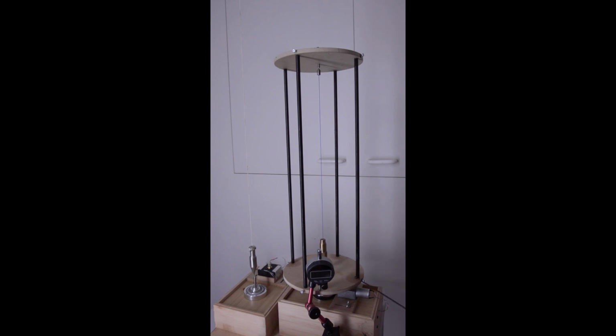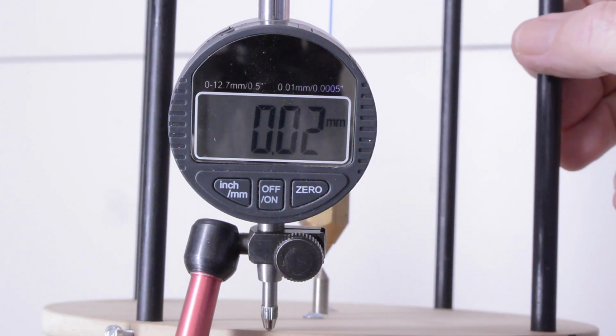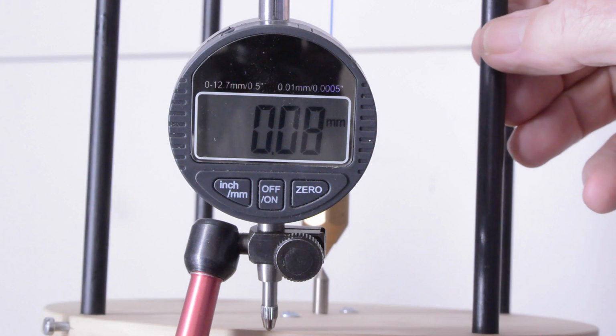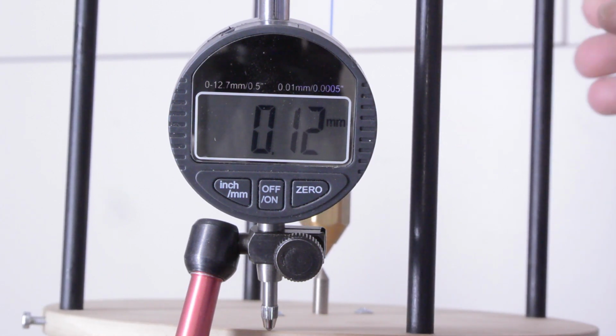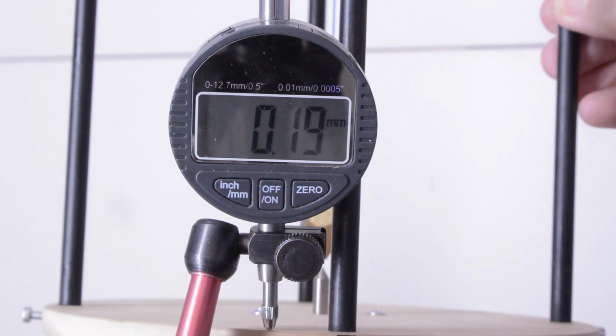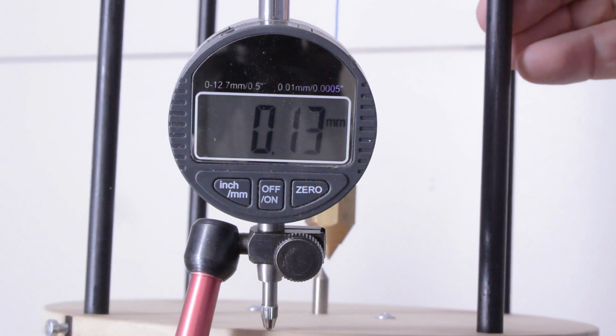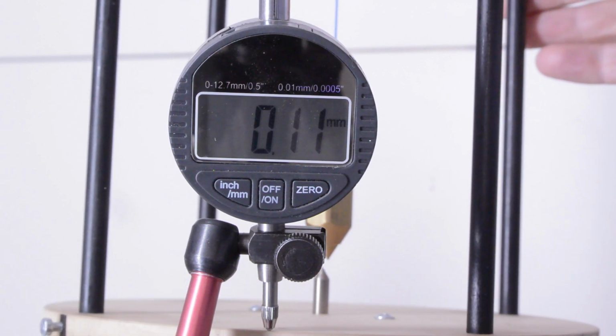So, alright, let's just now move to the dial indicator, and I'll just show you this run out, which may help you process the data. So stand by as I set up for that. Alright, I've just zeroed the dial indicator, and we're getting 0.04, 0.08, 0.1, 0.16, 0.17, 0.18, 0.2, there's a bit of a flick there.